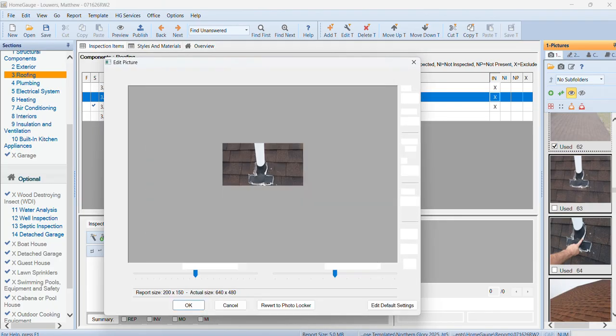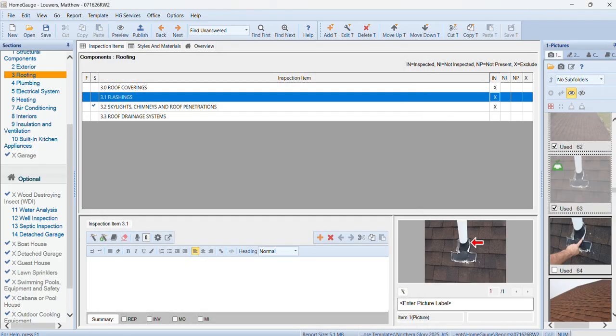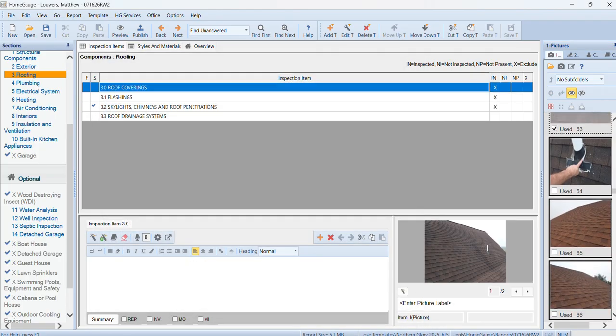This flashing, it's all sealed up with caulk. I peeled that caulk up. Now you can see this flashing terminates below the row of shingles here. There's absolutely no need for this caulking. I peeled that caulking off the top of that flashing to just look and make sure that the upper part of this flashing was under this row of shingles here, and it was. So this caulking is useless. People just don't know enough to know that they don't know.